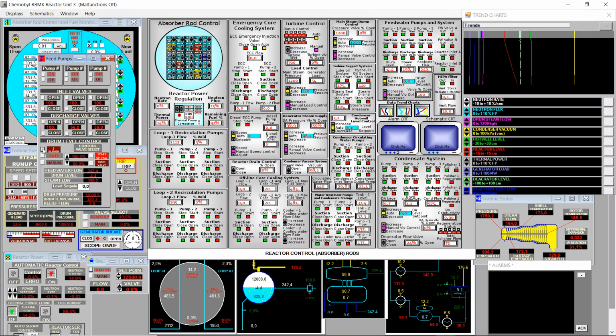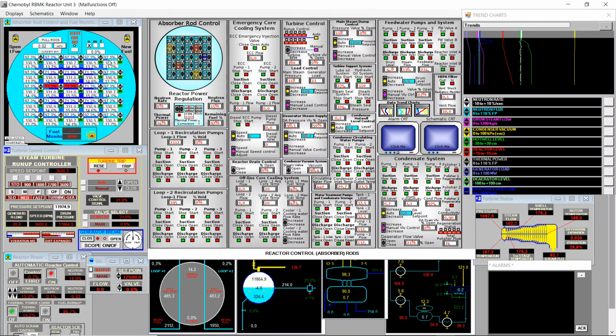Then we need to switch on the 3-element control. We leave this in auto, and we go into the main valve in the drum level control. The set point is fine at 0, and this is fine. Then for the turbine control valve select, we need to select main. We were in the startup for the startup procedure, so I select main, and you will see as main opens, startup is closing to keep the discharge what it should be.